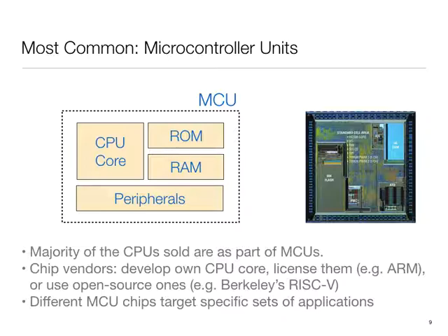There are also companies like Atmel and Texas Instruments, who make processor families, such as the PIC microcontroller and the old Intel 8051 series. So those are also very common. But I think the more interesting new entry is the RISC-V that I mentioned earlier, an open source design. You can support it on a lot of FPGA boards, or if you want to spin your own silicon, you can do it. It's pretty tiny and efficient, and there are compilers and operating systems supporting it.